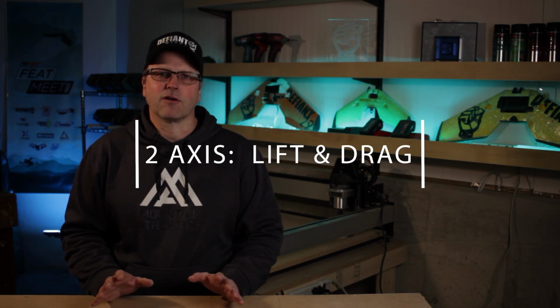Basically, this will be a mechanical balance with some digital strain gauges that'll be connected to an Arduino board. And while I'm at it, I'm going to go ahead and get some airspeed data, some temperature data, and some angle of attack data. All of this is going to feed through an Arduino controller, so there'll be some Arduino programming. And then this will all go to a computer interface so that I can record the data and graph it. So that means I'll be developing an interface also to run on the laptop.